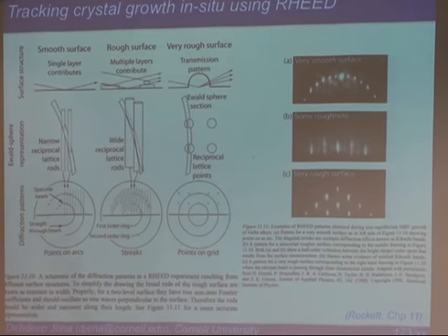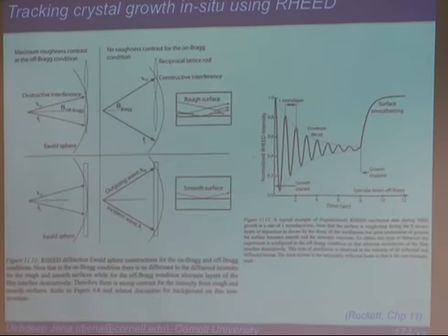So it actually oscillates between the two. The intensity will oscillate. When you zoom into one spot and measure its intensity, you'll see these oscillations. These are RHEED oscillations, and obviously, as you can see, they let you count how many monolayers you are growing as you are growing it. This is extremely useful and tells you the growth rate. If you want to grow a 3 nanometer well, you can grow 3 nanometers and stop. If you want to grow 8 monolayers, you grow 8 monolayers and stop. So it's extremely powerful because of this particular feature.